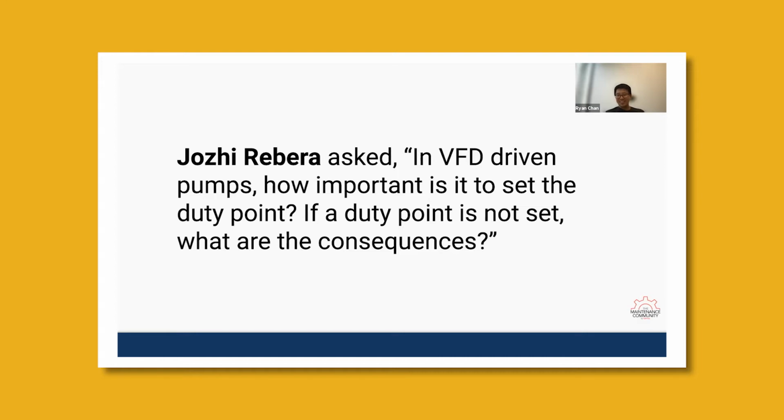Yeah, I think it's a very specific question to VFD. Now, let me explain for people who don't know what VFD means: variable frequency drive. Why do we use a VFD? It helps us reduce the speed of the drive unit so we can change the flow or pressure. So really, a VFD helps us reduce our energy cost. Usually what you look into is your pump performance curves. You have to match so you're not going below the performance curve with the speed. So you need to have a flow rate or speed and see where the performance curve falls down, so you don't go below that.